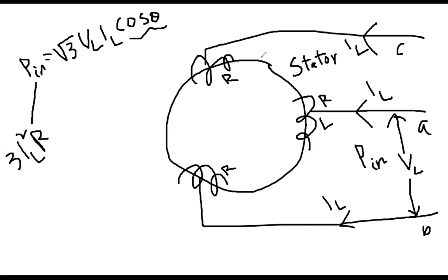And then you see this circular body, this is the core material. So it has eddy current loss and hysteresis loss. Therefore, from the input power, you subtract this one, and then again you subtract the core losses, meaning the eddy current loss and hysteresis loss.